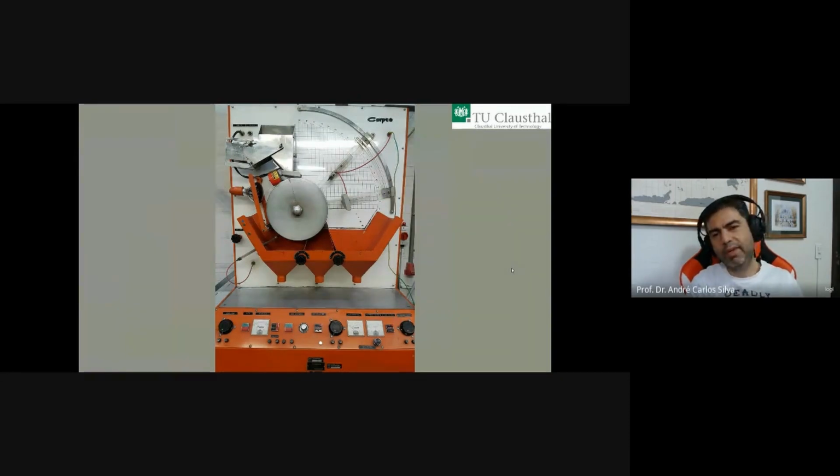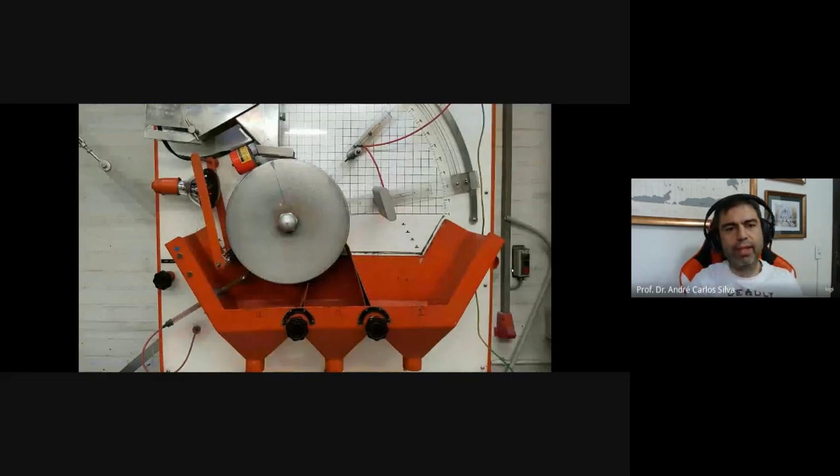I tried to separate my rare earth on this machine, and I completely failed, because, as you can see over here, I was supposed to have 3 products, all in the base of the equipment, on the lower part, and I have this feeder right here on the top. I can adjust the angle of these 2 electrodes, the corona electrodes in here, and then the second electrode over here.